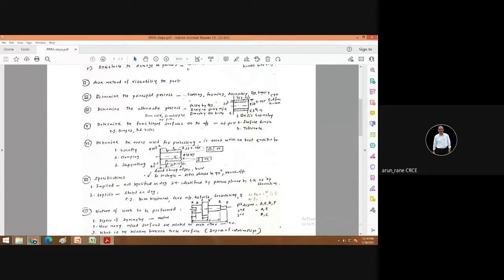See, if I tell you to come at 11 o'clock dot, the probability of reaching at 11 o'clock may be very less, 1% or 2%. But if I say come between 10:55 and 11:00, plus or minus 5 minutes, the probability may be 80% of reaching in. So same thing is manufacturing. You cannot manufacture 0, 0. There are a lot of factors: machines, materials, man, tools. So suppose a bore is given say 100.00 plus or minus 0.04, or say same example 25H7, so 25 plus 0.018. The moment you look at the tolerance, this tolerance is close. That means again it is going to be a functionally important surface. That means something is going to fit inside this. So you have to pay special attention. You have to be careful.